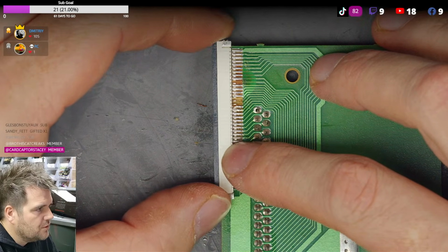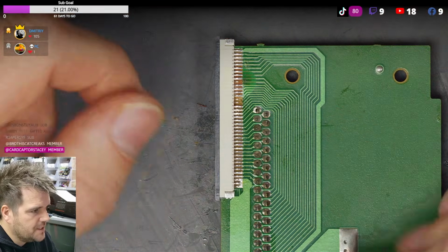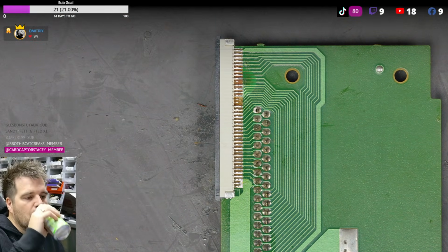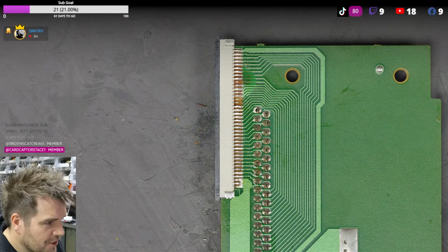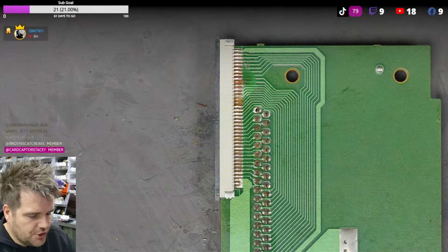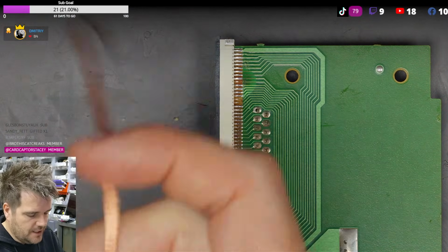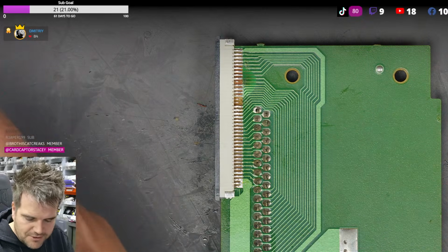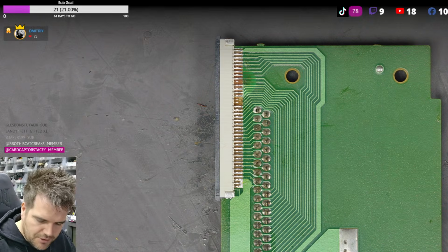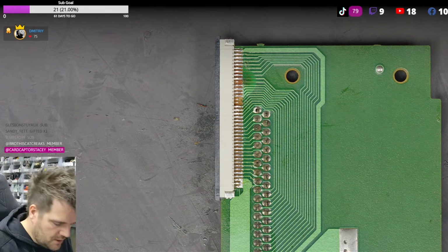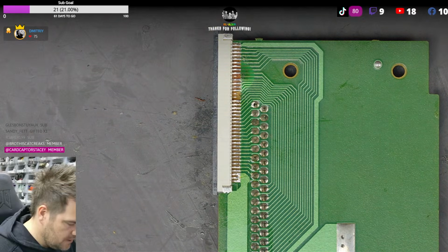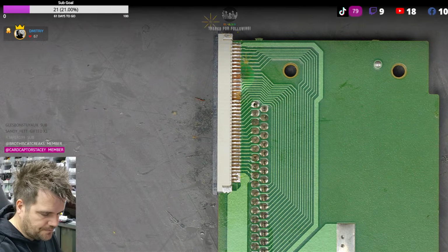Yeah, we can use low melt solder as well. I've got tons. I'd normally use hot air. I was just kind of showing the technique with the soldering iron, but I'd hot air those connectors off. But because I showed the hot air in the last stream, I thought I'd just show the soldering iron way at the start just to give you an idea. But yeah, I've got massive sticks of low melt solder, again from a factory where I get most of my stuff from. So huge bars, but I just never use it. It's not something I rarely need or use.